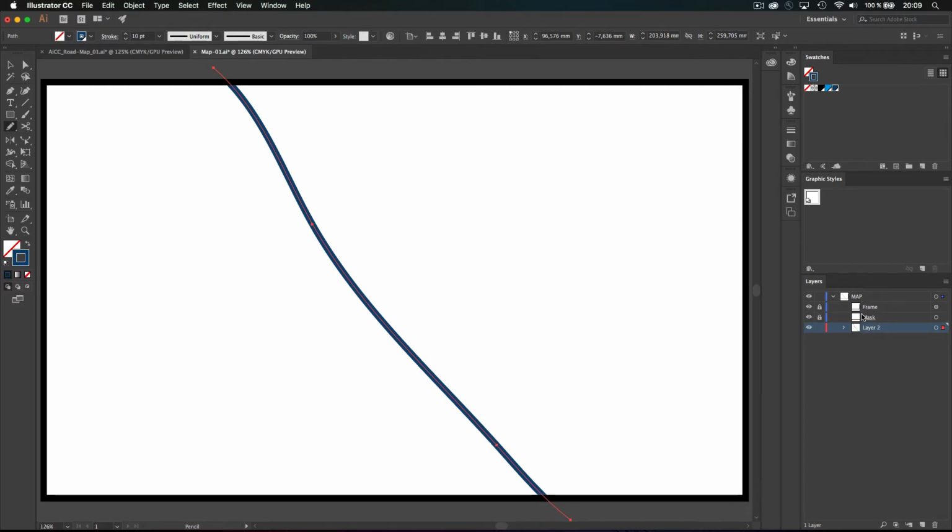So that's cool. Just also to let you know, when the mask is created, you can put the mask at the bottom. That doesn't matter. You need to have the shape to build your map on top of the stack, inside the layer at the first position to create it, but after that you can put it at the bottom, and that's not an issue. And don't pay attention to this. It's a small refreshing bug. Normally that needs to be blue. So that's it. So now I'm there.